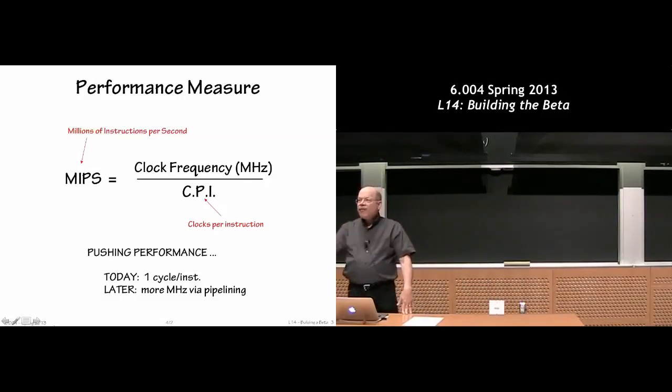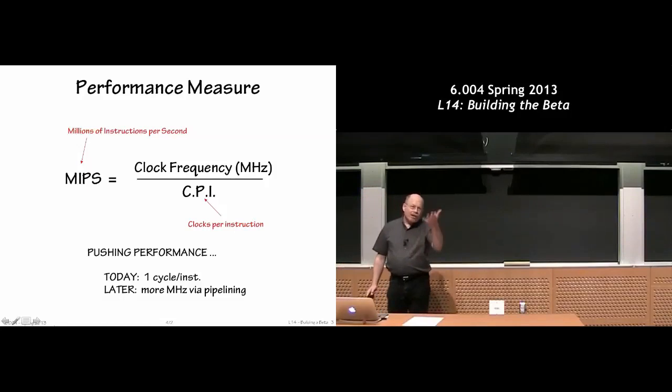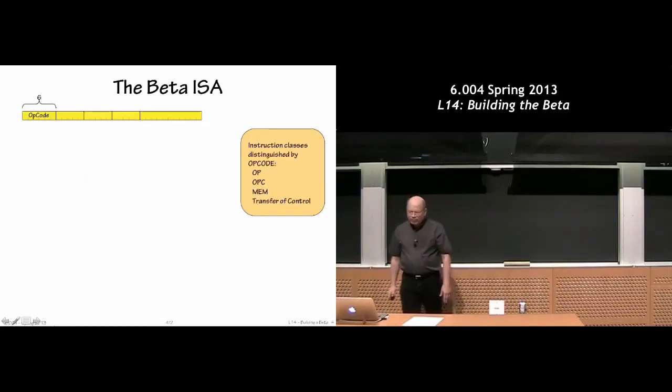And the machines that you have in front of you, in your laptops, have a 20-some-odd stage pipeline that they're executing instructions in. So their clock rate is about 20 times what they'd be able to achieve if they didn't use the pipeline at all. And that's part of what makes your computer so fast.